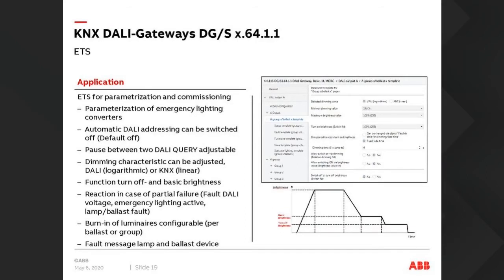And again, in the application, you can play with the various settings. You can have the switch on speed, you can have the switch off speed, you can vary all these. As I always say, when I walk into a room, I like the lights to come on quickly. I don't want a light dimming on slowly, so I want a light to come on within a second when I come into a room. However, when I'm leaving a room, I'm quite happy to turn off the light and let the light switch itself off over 5 seconds, and it creates a nice effect, and you can create some nice effects in a room by doing this. And I suppose for the end user, they see the value of what they've installed, and they get nice switch on fast, switch off slow. They get all this sort of stuff.